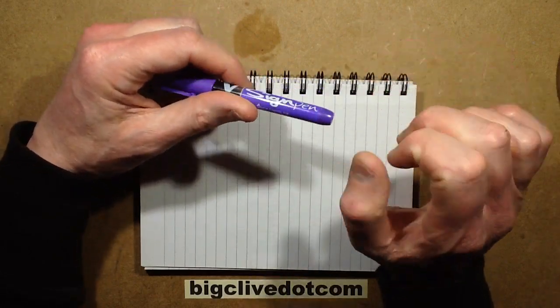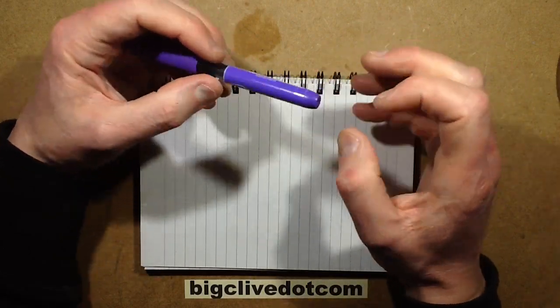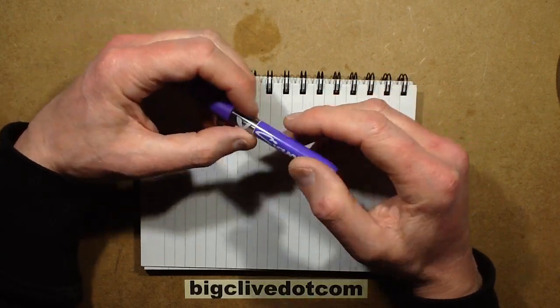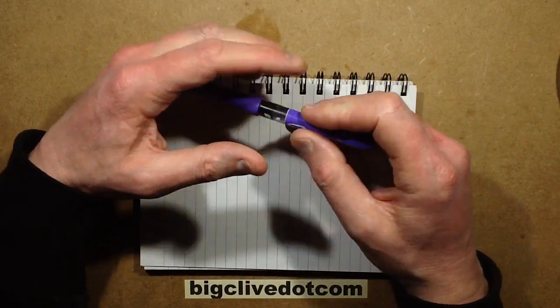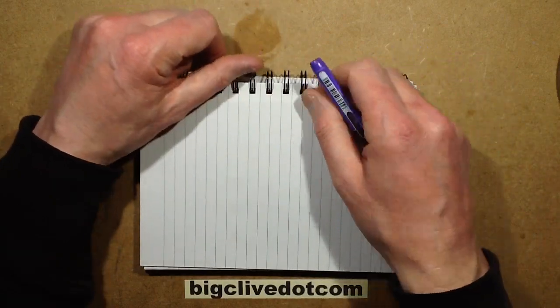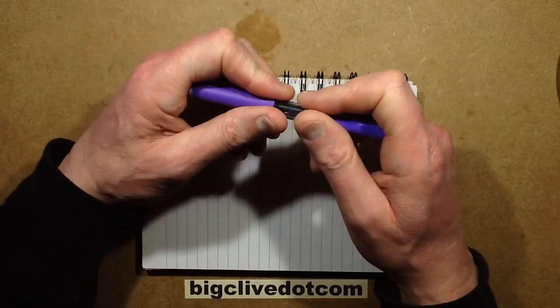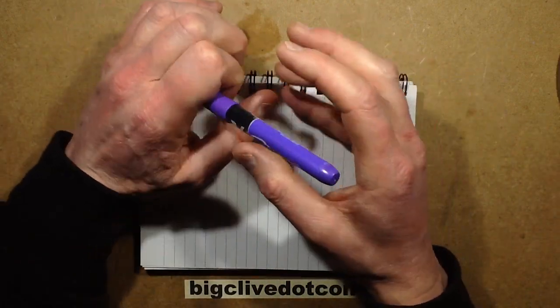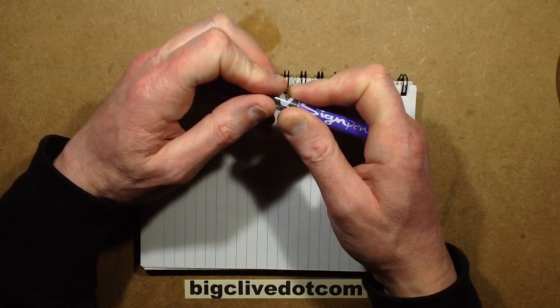The main requirement is that they're made with distilled water, very pure water, and good quality, sort of medical grade glycols. You don't want just generic random industrial chemicals with lots of impurities, because you just don't know what you're getting into the air. And one of the most common failure modes of smoke machines is blockage, heater blockage.